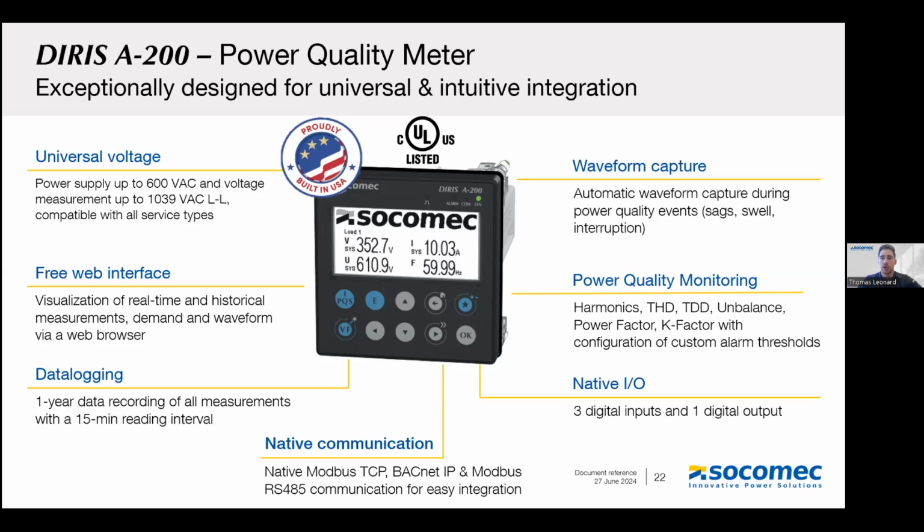For all these measurements that we're talking about, harmonics, unbalance, power factor, the meter can have custom alarm thresholds created. So if you want to be alerted as soon as a threshold is exceeded, as soon as there's a high value or a deviation, that's something that the power quality meter, the A200, can do. It comes with native, standard communication: RS-485 Modbus RTU. It comes with dual Ethernet, Modbus TCP, and BACnet IP for easy integration to most of your SCADA systems, EMS or BMS software.